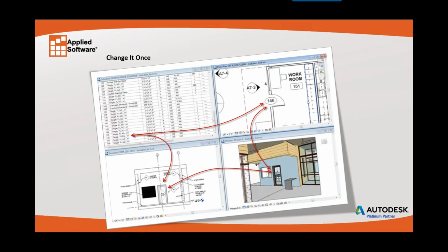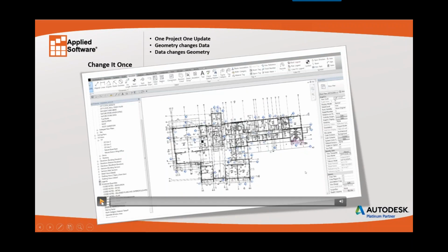In this screenshot here, you'll see in the top left-hand corner, going around clockwise, I have a door schedule. That door schedule is associated to a smart door in this workroom. Notice the door number is wrong. Okay, we'll look at that later. And then it has a 3D elevation, which helps the client understand what this space looks like. And then finally an elevation. Any change to any one of these views will have an automatic effect to the other views. Again, it's one file, one model. And this is AutoCAD. This is Revit. So let me go through and show you this brief little video.